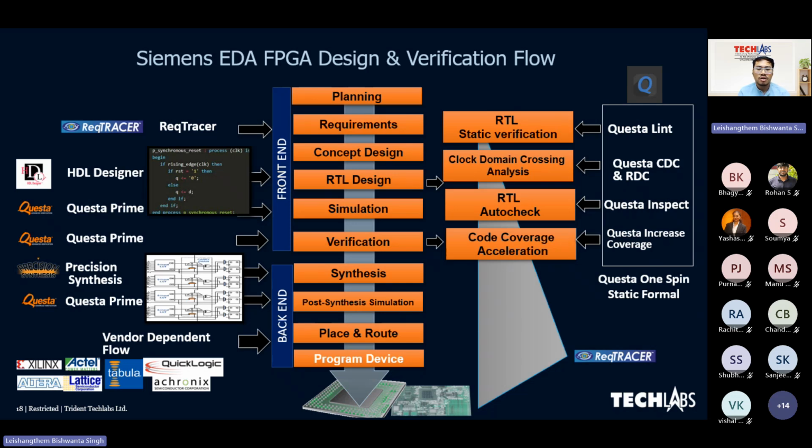Once your RTL is done, the traditional flow is to go ahead with simulation and verification, but DO-254 asks for more than that. It involves an analysis process, actually lots of review and analysis, your validation at the RTL level itself. So on the right side, we move on from the RTL design, and before developing the testbench environment or testing the RTL design at the behavioral as well as at the hardware level, we will be performing RTL static verification in compliance with DO-254 again. This is very important. Your RTL has to be in compliance with DO-254.